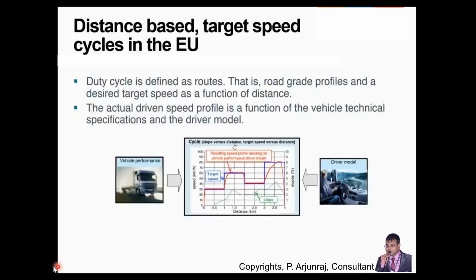So based on some extrapolation, if you measure the wear up to 20,000 kilometers at an interval of 2000 kilometers, you can extrapolate the wear pattern, comparing the initial wear to the wear at 20,000 kilometers, and see whether it is crossing beyond the 40,000 tire life or coming below 40,000.